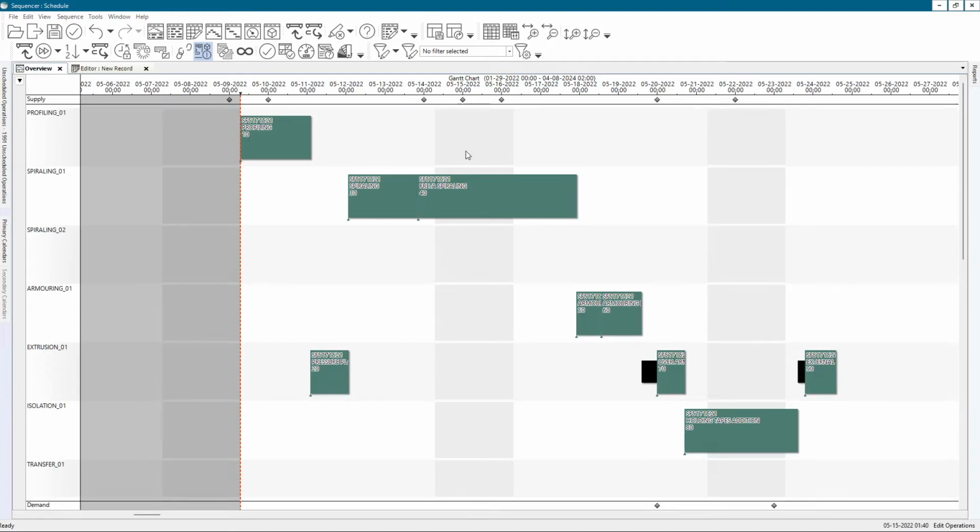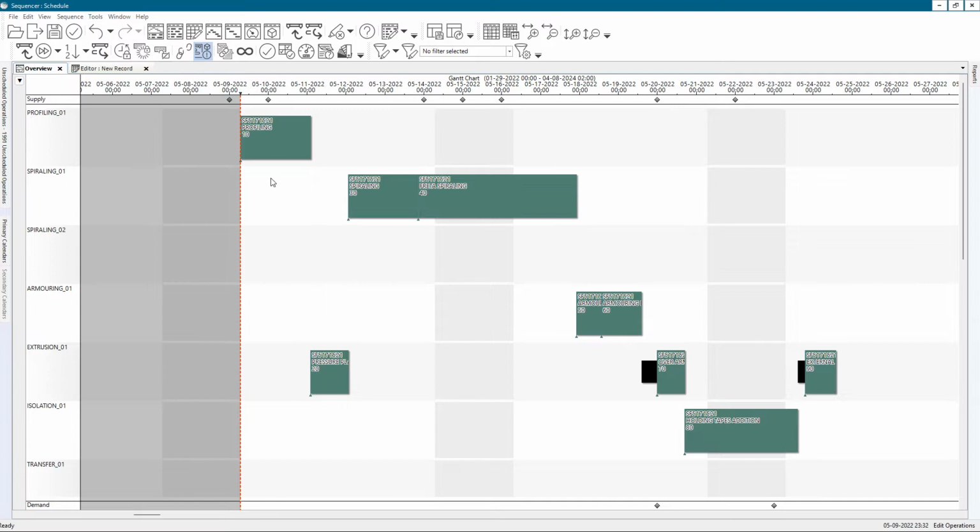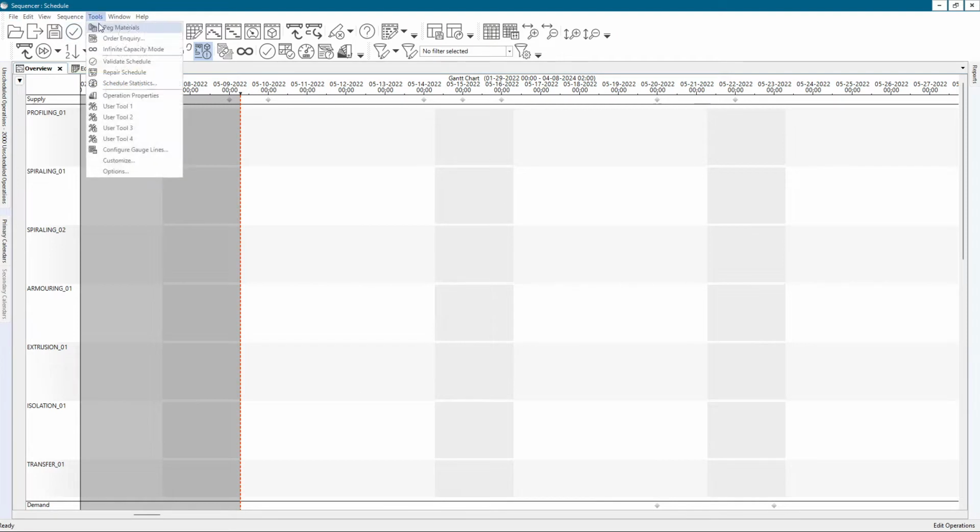The standard way for Opcenter APS to create links between operations is using the operation number. Remember that we have links between orders and links between operations. So for example, here we only have links between operations because I have not run the pegging rule. So I don't have, for example, links between the supply to here. Let's do that so you understand the difference.